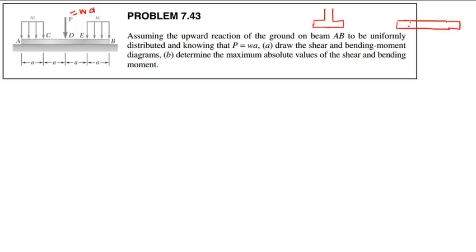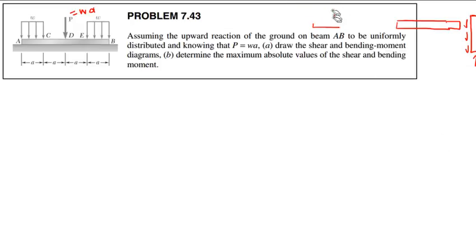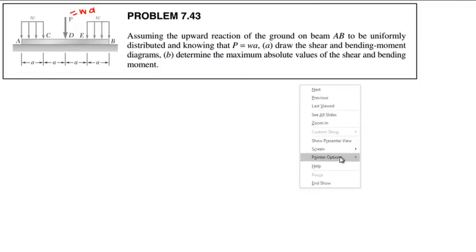Sometimes you see beams built into them. Or you can use deep drilled piers, if you really want a stable structure or if you have really bad soils. These are supported by a point force at the end and skin friction along their outsides. But anyway, they all have the commonality that they're supported by distributed loads like this.